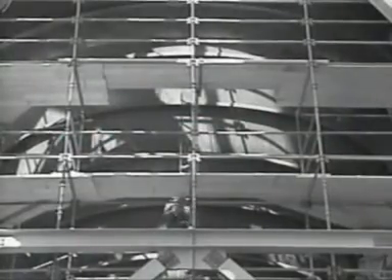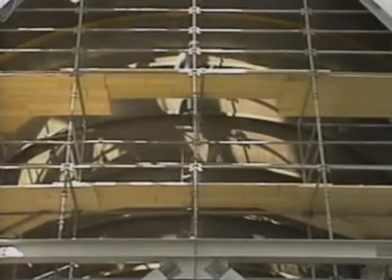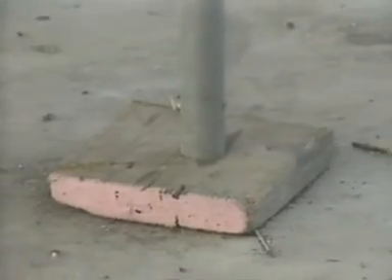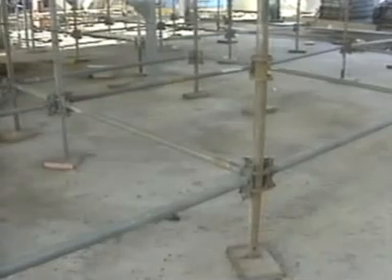The upright supports and horizontal members of stationary scaffolds must be square and level. All cross-bracing and diagonal bracing must be correctly assembled and securely attached to create a strong and rigid structure on which the scaffold platform can be placed. It's critical that the footing and anchorage for stationary scaffolds be sound and capable of supporting the maximum intended load